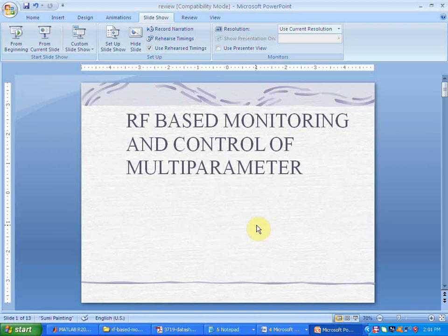So you need to detect this. Once the zero crossing is detected, that zero crossing pulse can be used by the microcontroller. Based upon the distance between the two zero crossings, that time value is used to calculate the frequency. So this way the frequency module works.